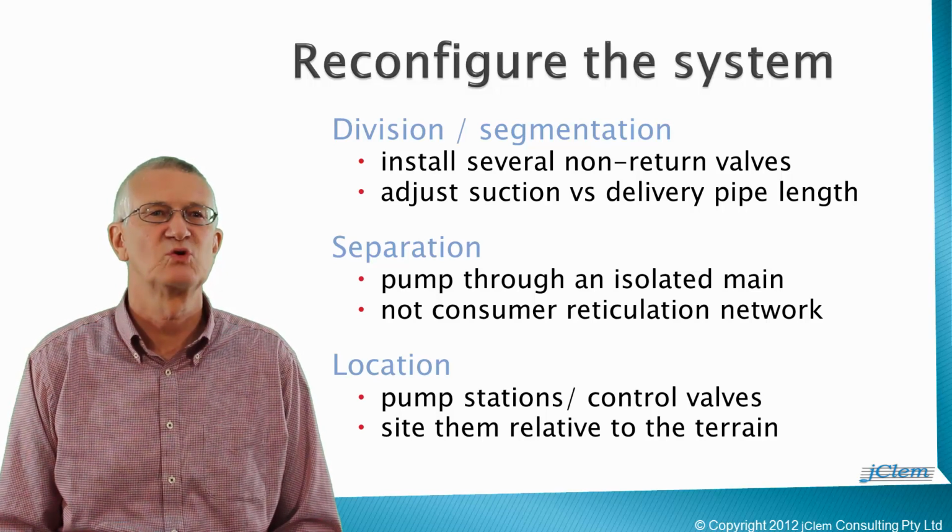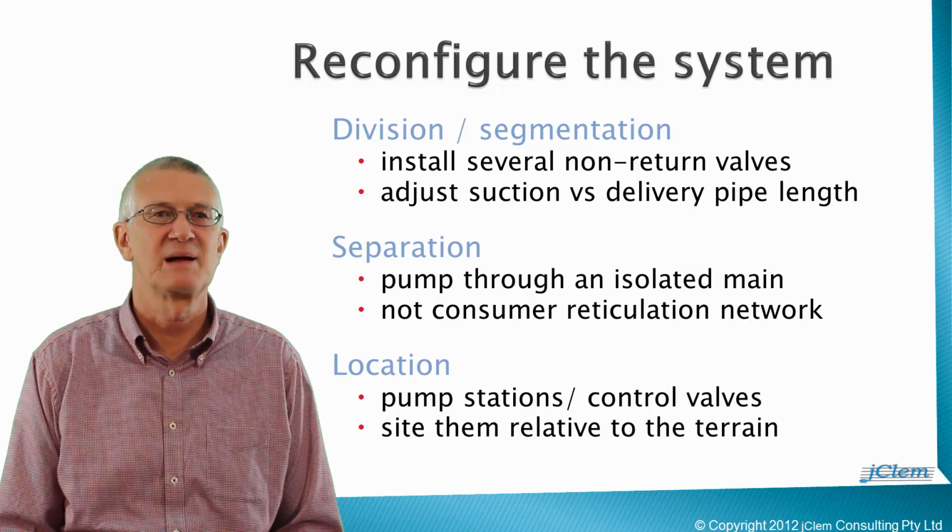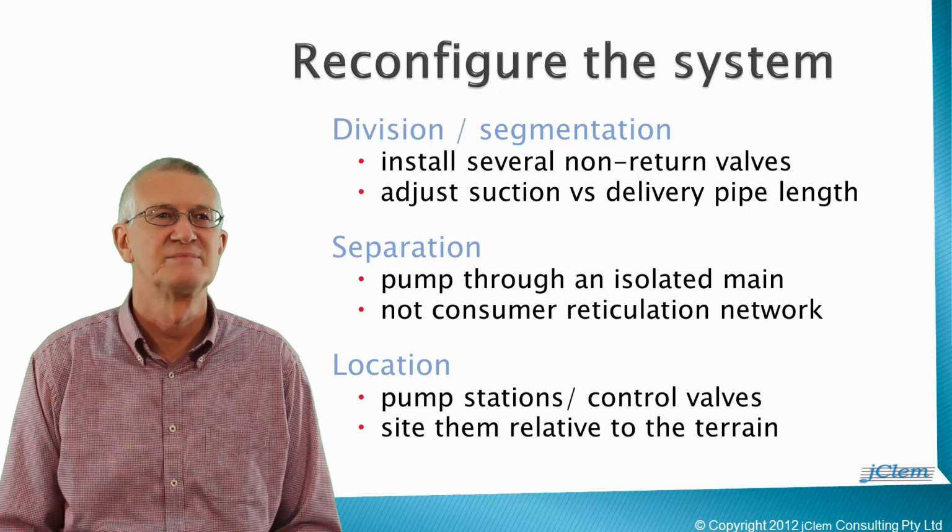In a pumped drinking water system that has the choice to supply customers from a high tank or the pumps that refill the tank, instead of pumping through the customer reticulation pipe network, pump through a separate pumping main. On long pipelines across terrain with significant changes in land elevation profile, set control valves and pump stations in locations that enable the surge envelopes to best match the land profile.